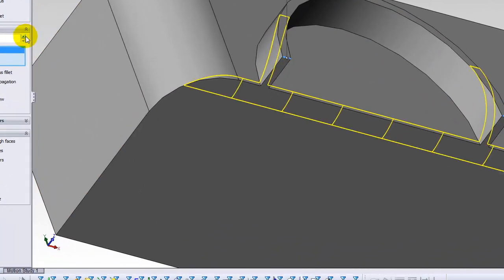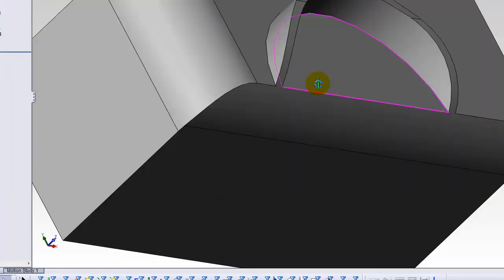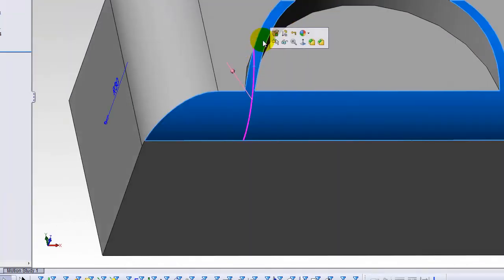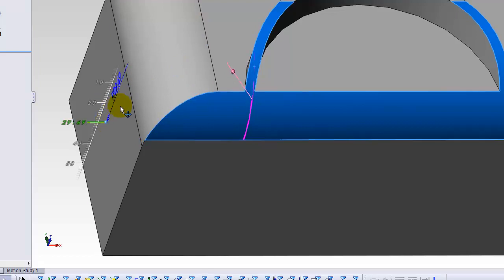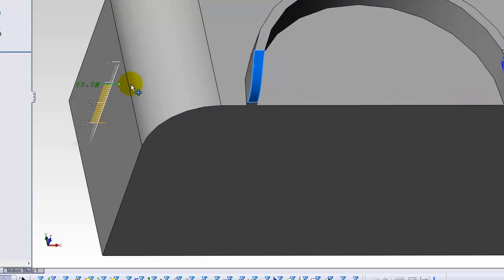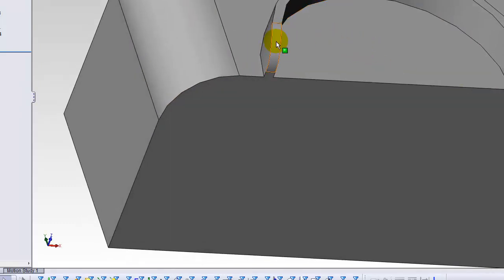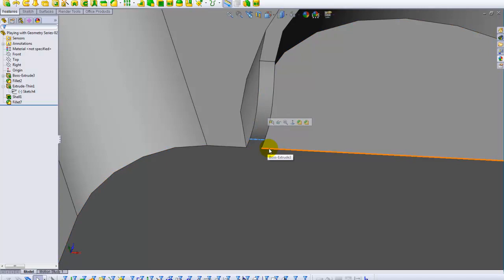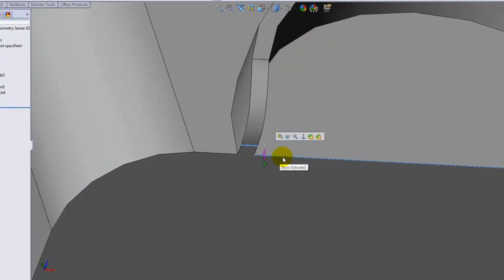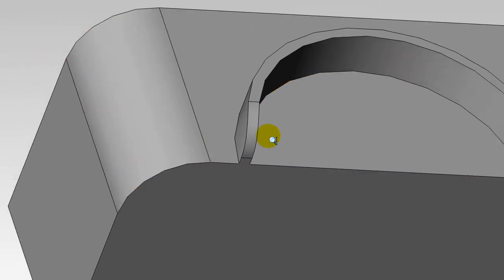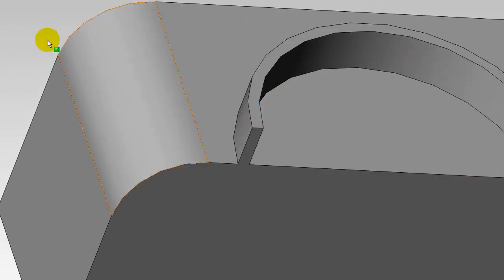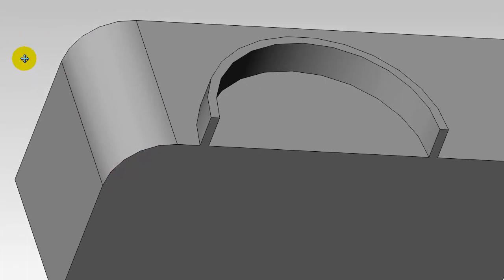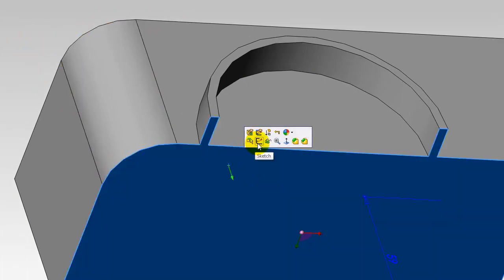We can play with its geometry, and it could be anything like that. But in our case, and let me take it back here, we need a specific limit for the radius. For example, the end of the radius has to have a 2 mm offset from this edge. So how can we make it? Indeed, there are many ways of doing the same things in the CAD world, but let's use one simple way.